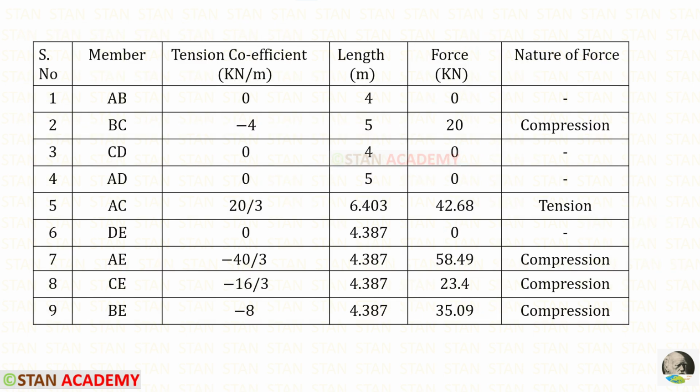Now we have to make this table. In the table, first we have to enter all of the members. Then we have to enter all of the tension coefficients. Some of them are zero force members.